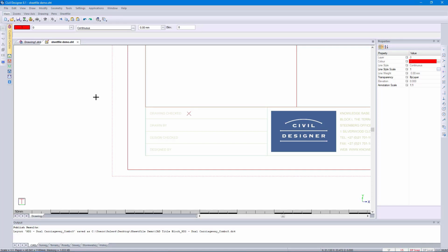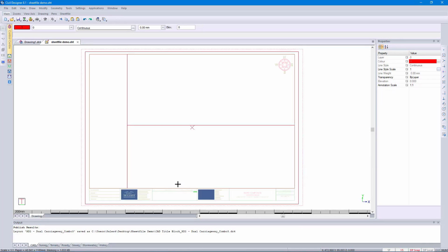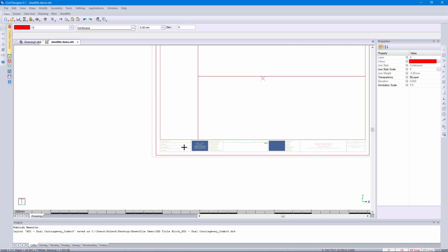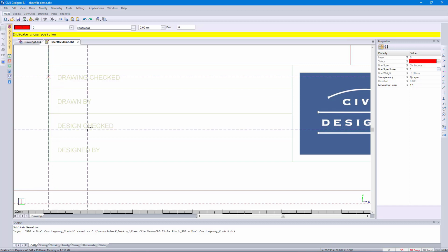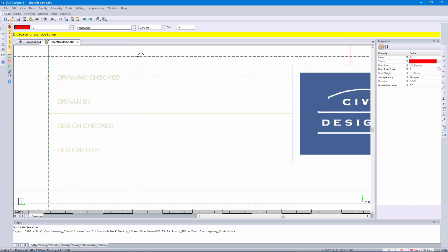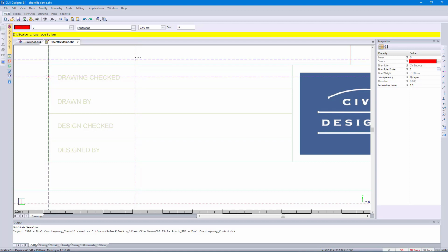Okay, I'm going to place some prompt questions into the sheet file. So when the user creates the layouts, they'll be asked certain questions, and you can choose these questions completely optional. I'm going to use the geometry cross and the O on the keyboard to ratio jump between 2 points. This is to find a suitable location for the text's hook point.